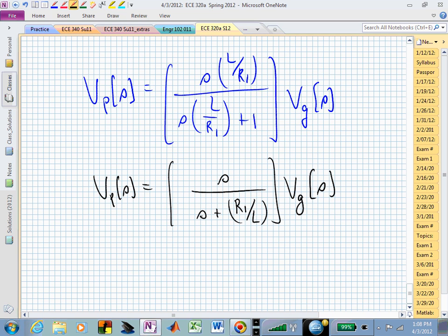So as a frequency response picture, it's coming up from below, and then when this pole kicks in, it changes that slope by minus 20 dB per decade, while I was going up at plus 20 from that zero, and now I flatten out.